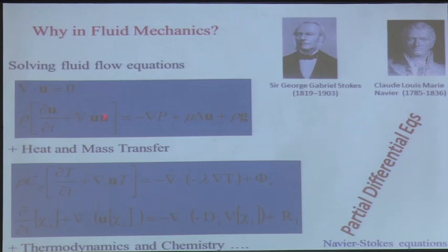They are 3D, three-dimensional, because the flow is very likely three-dimensional. They are time dependent. They are nonlinear because of that term, the product of u by u, or u by its derivative. They are dissipative because of that. And in terms of mathematics, I don't know if you know the classification of PDEs, you have elliptic, parabolic and hyperbolic equations, and actually in the Navier-Stokes equation you have everything. So they are not from one of these three families, they are part of all three families.